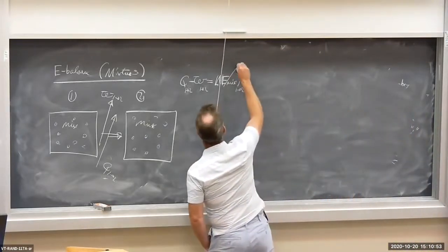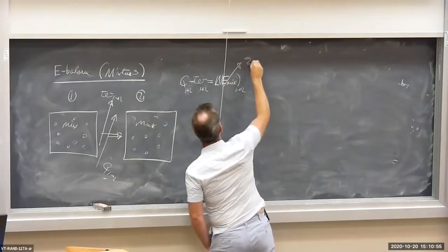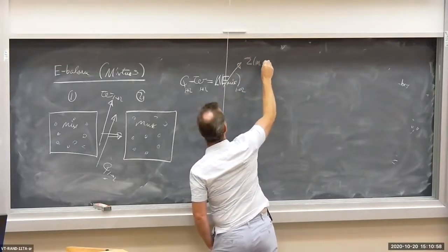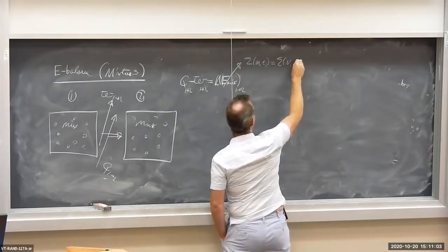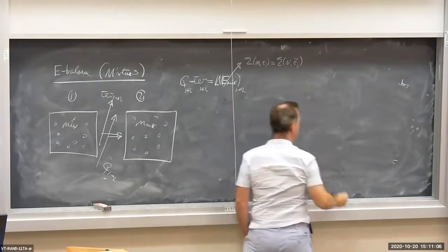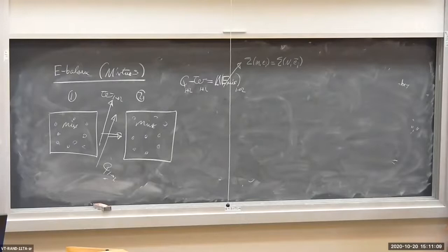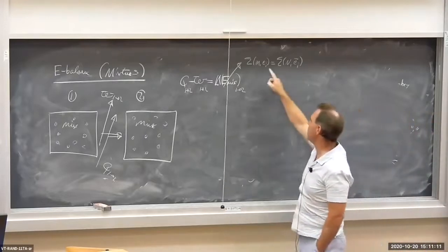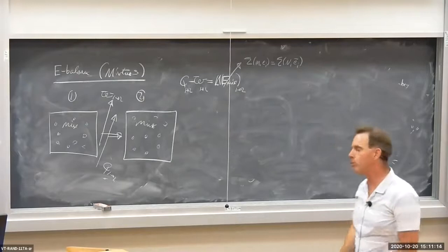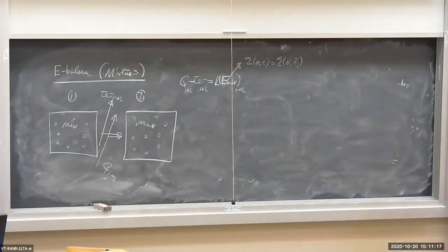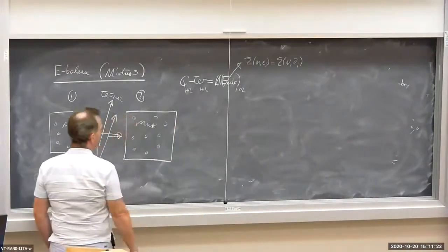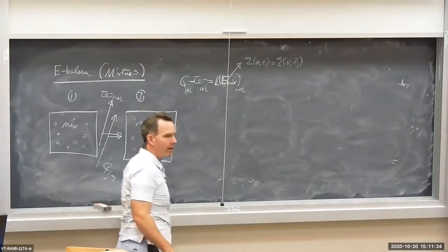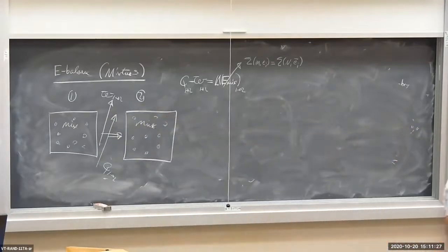So E for the mixture is the sum of either M I, E I, or the sum of N I, E bar I, okay? Usually total energy, specific energy is going to be internal energy. So you could put U's up there and I guess it would make more sense, okay? All you got to do is be able to calculate the total mixture energy before and after, and boom, you can use your first law as you normally do, okay?